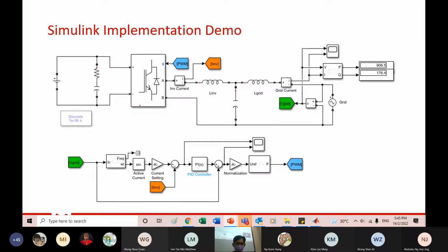Okay, similarly, our input is here, 400 watt. We have a capacitor to hold the energy. Without this one is still okay, but practically you will still need a capacitor to temporarily hold the energy. And the output. Now, when you have a grid connected inverter, we no longer just use L and C. We call it LCL.